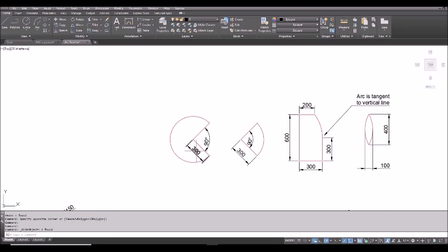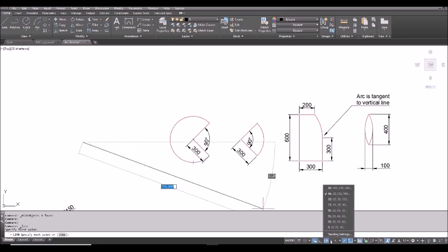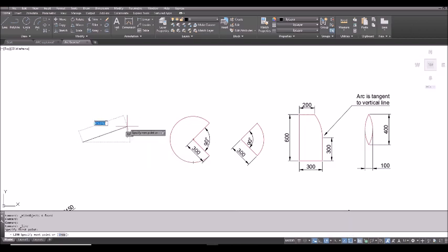So next exercise. To start with, I draw the line first. I can see the line is 45 degrees. So L, click any point and position 45. To make this work, make sure you click on the polar tracking and select 45 degrees. Okay. So I put it 45 degrees like that. You can see the green line, and I will just type in 300.